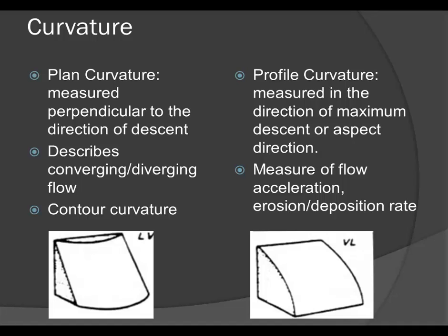In addition to slope, there are two other topographical indices that are important in terrain analysis and are derived from the gridded elevation data. They are profile and plan curvature, that are useful in measuring or predicting soil water content, overland flow, rainfall response, distribution of vegetation, and so on.